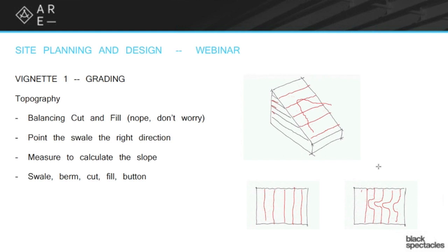But you absolutely want to be very clear, because you will not pass the exam if you get that one backwards. So that's pretty simple and straightforward. You can maneuver water through a berm, a mound, but 95% of the time you're going to be doing it through a swale. So you're going to be making ditches that specifically function as a way to gather the water, right? So why does a swale work? Well, the water is always going to find the lowest, closest slope, the way to get down fastest. It's using gravity.